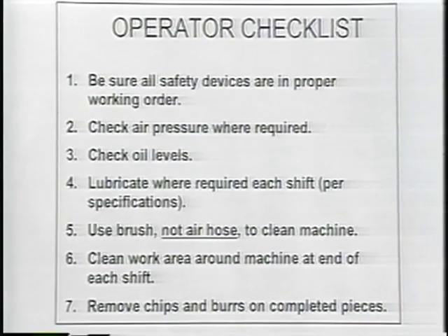Irrespective of how it's accomplished, that's a permanent step that must be done by the machine operator. They also lubricate, per specifications. So there is going to be a separate PM spec tied right in with the lubrication media, such as the container that the lubrication is in, or let's say some type of a pressurized pump.